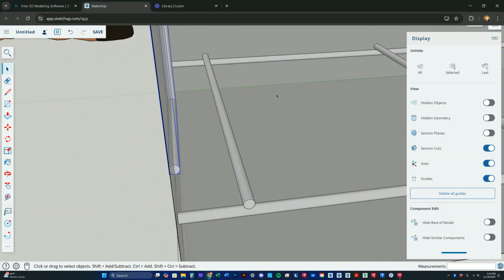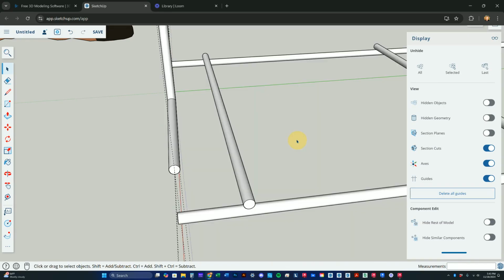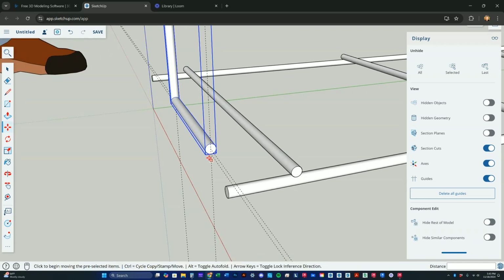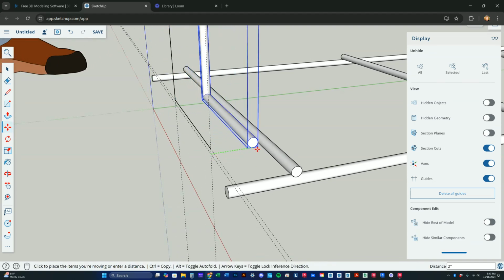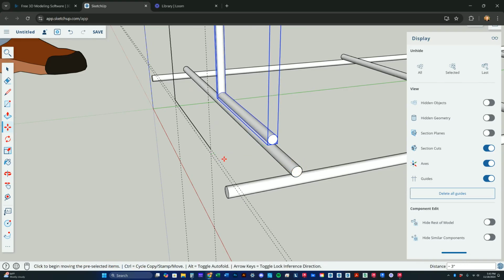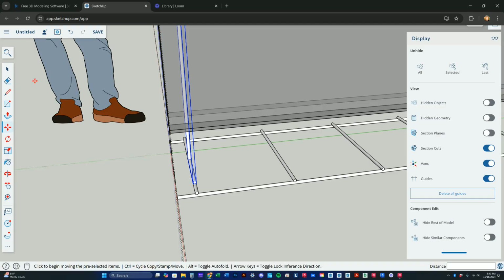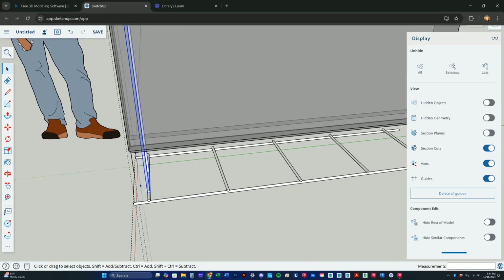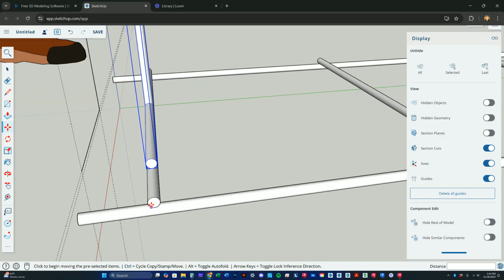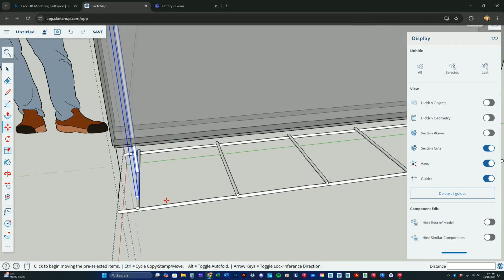So for a second, let's pick the footing and hide it. And then we're going to grab this, and we're going to move it in so that it is on top of this. Now these are only at 32 inches on center, where these were at 16. So in order to copy this, we grab the move tool, and we can either grab the ends of our circles and do every other one, or we can just hit control and move